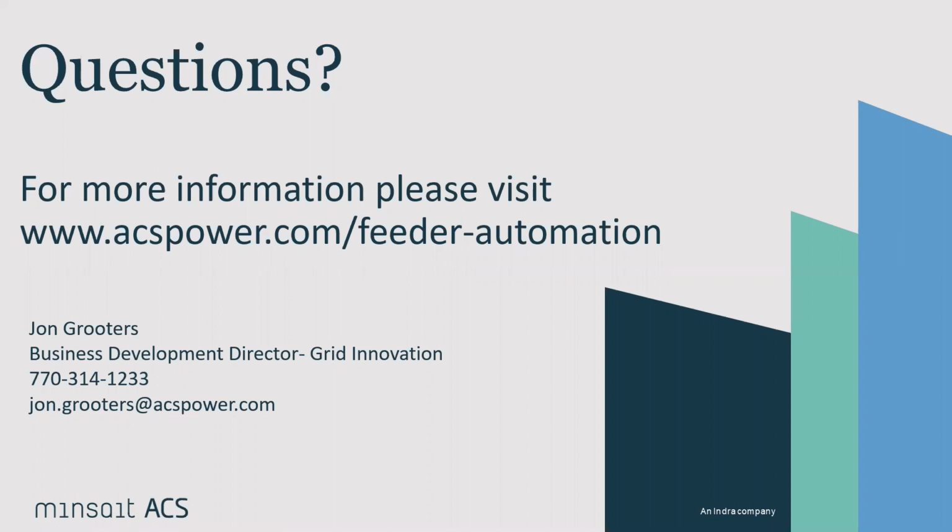essentially a software RTU that's part of our Centrex host that facilitates real-time communication between the Centrex host platform and the existing SCADA system via DNP over IP. So it doesn't require any type of more complex interface, whether it be ICCP or MultiSpeak. It's a simple DNP link. All the real-time information and commands are exchanged between SCADA and Centrex via DNP. And of course, there's the real-time GUI you saw during John's presentation.